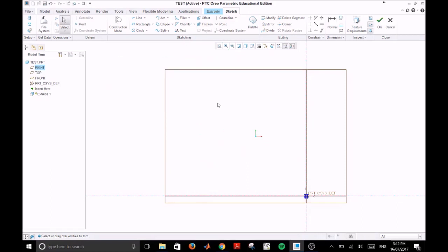Delete. And have a look at the circle tool. There are several methods of drawing circles. The most convenient one is normally the center and an outside point. So we know our origin. We can click once and then drag to make our circle, clicking a second time.